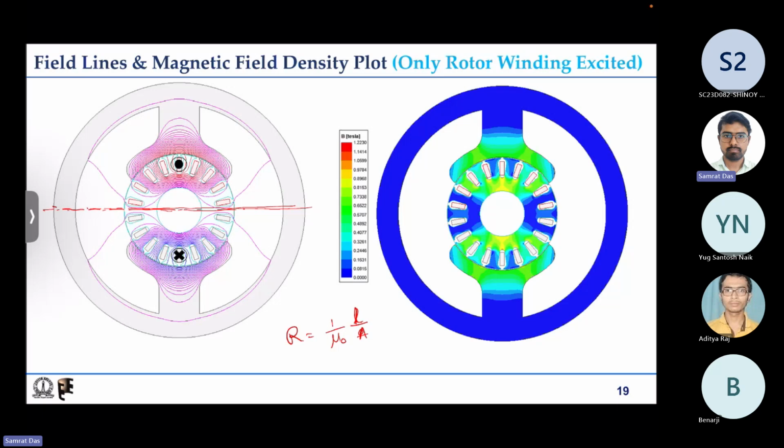In these cases where length is quite big, if the air gap length is quite small, then it is quite easy to assume the flux line path, and thereafter we can calculate the area. For example, if we have a small air gap, say a pole like this, which has some surface area.